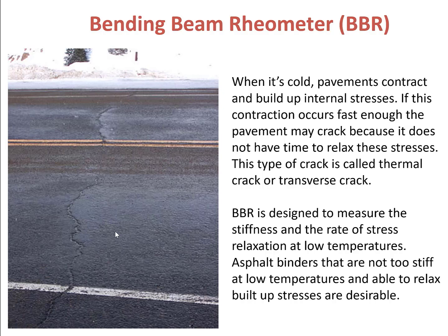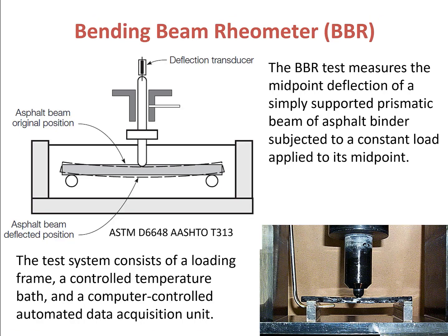Asphalt binders that are not too stiff at low temperatures and also able to relax the build-up stresses are desirable. The BBR test measures the midpoint deflection of a simply supported asphalt binder beam when it's subjected to a constant load applied to its midpoint.